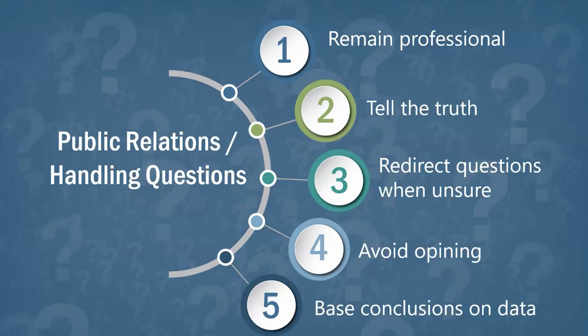So the process at my facility was to follow the EPA guidelines, which was that if it was less than 10 square feet of surface contamination, we might handle that in-house with our trained persons. However, if it was any more than 10 square feet visible, then we were immediately going to get an indoor air quality assessment by a third party, because we don't want those things to influence. We don't want the fact that the person reported this is a habitual reporter of hazards to influence us in whether or not this is a real hazard.